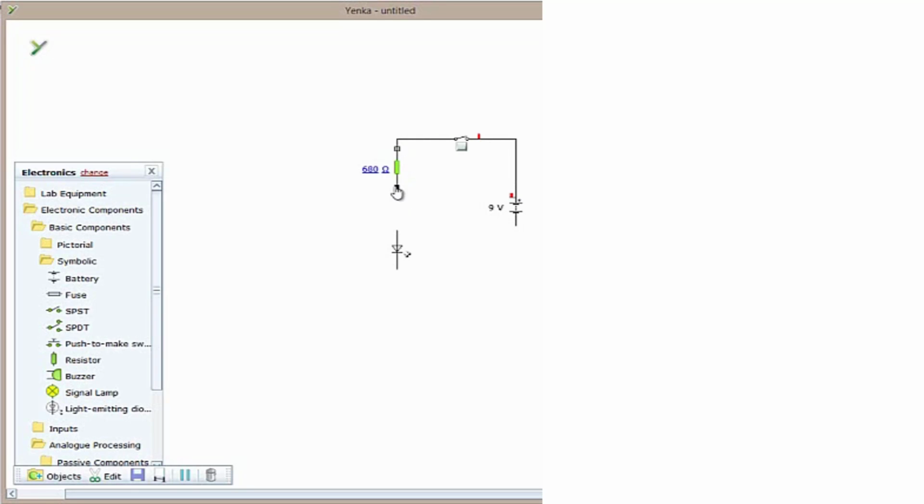Okay, so let's just connect those up and demonstrate that we've got a functioning circuit. We complete the circuit, close the switch, and a light comes on. I'm going to change the value of that resistor there to 470 ohms, which protects the LED, but whilst still allows enough current to pass for it to give a nice bright light. Okay, so that's a basic circuit. However, it doesn't in any way react to light or dark conditions.